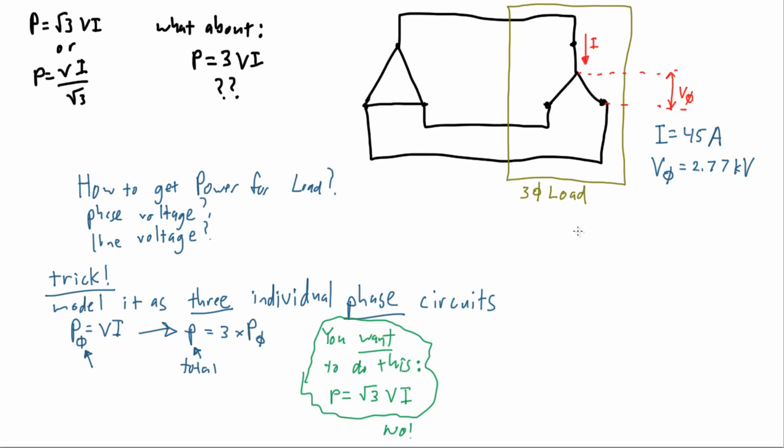So when we look at this problem, we should see very clearly that with the givens, we have been given all of the necessary information to derive power at one of the phases of the load. We don't need to do any conversion. We don't need to work from line to phase to line, anything like that. We have load phase values that can give us the power per phase. And so it really becomes a simple power calculation using our voltage and current on the phase given here.